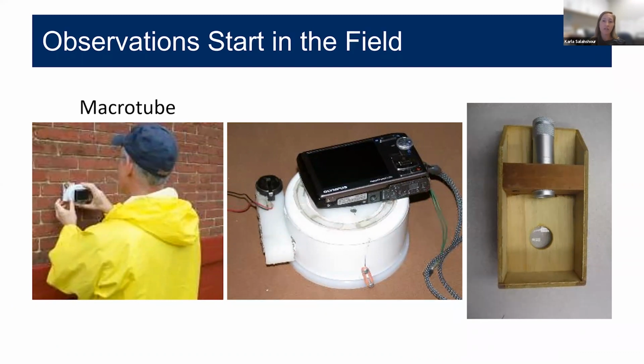And anyone can use methods that we use in the laboratory that can easily be adapted for field use. And so someone who is trained to look for certain features can be very valuable to the project team. And so we recommend, if the budget allows, to allow lab or testing staff to visit the project site and be present, especially during sampling, to make sure that the extracted samples are the best choice for the problem at hand.